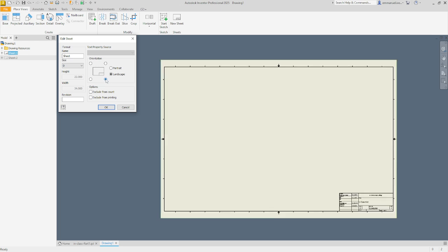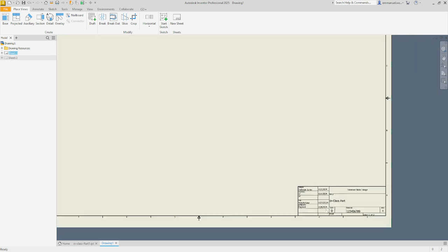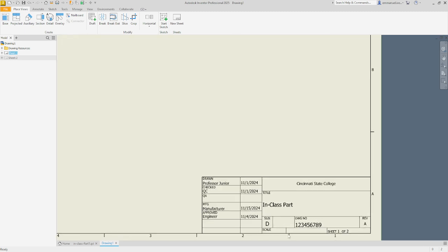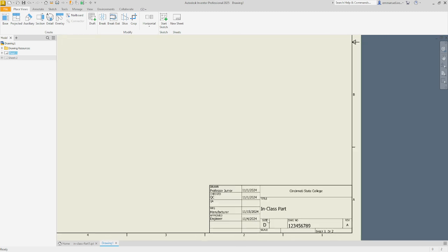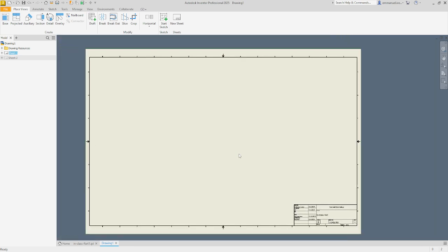which is standard for like 90% of the drawings that I've come across, or you can change it over to the left, the top left, top right. But like I said, I'll just go ahead and keep mine the bottom right there. Then I hit OK. And if I did make any changes, then that would display in my title block. My size drawing would change, and then my sheet orientation would change as well.